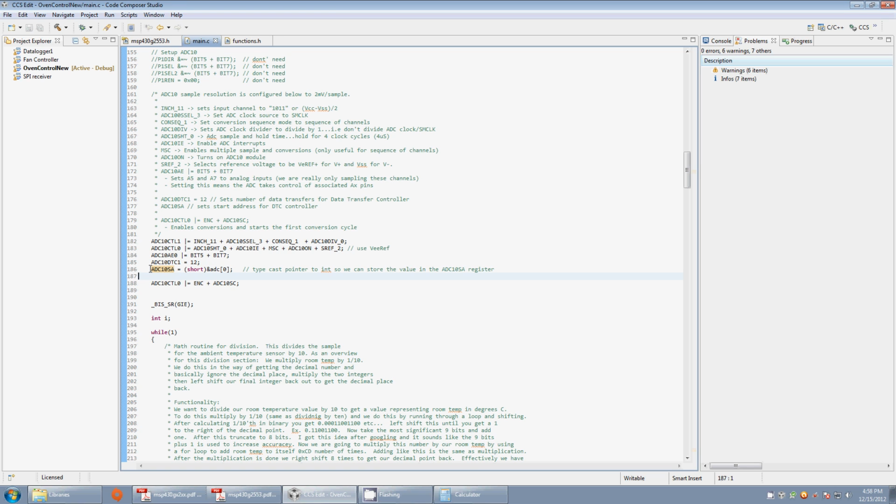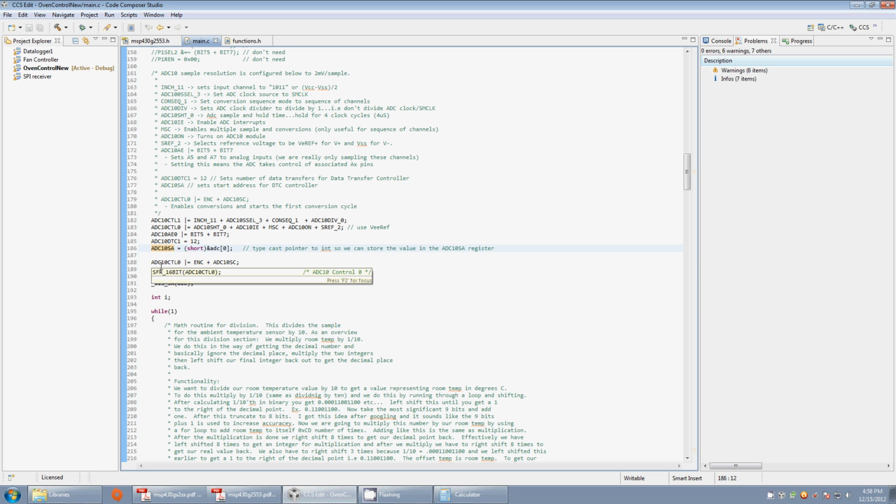And so that's pretty much it for the configuration of the ADC. The last thing we do is enable it and tell it to start conversion. And in the datasheet it says you can do these both at the same time. That's why I did it, and I just copy and paste it, so you may see this line over and over again. But so now we can start conversion. And the last thing we do is enable global interrupts here. And our system's up and running and ready to go.